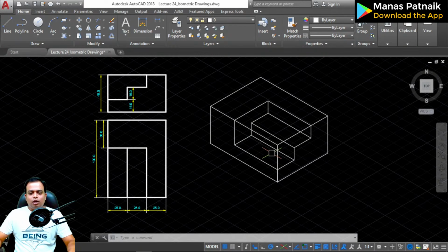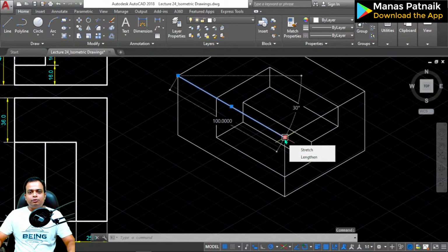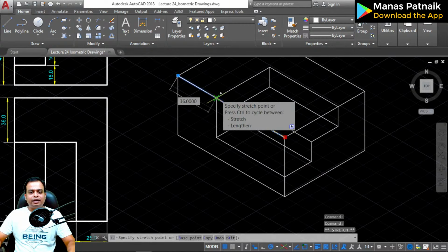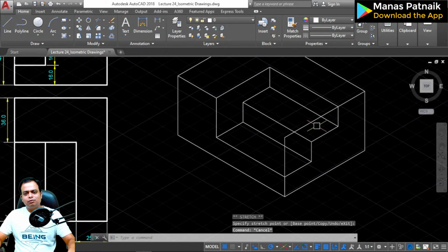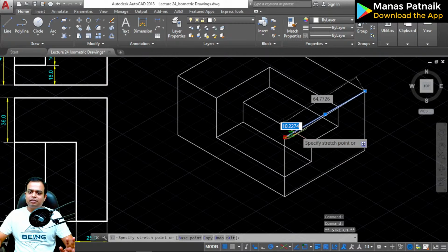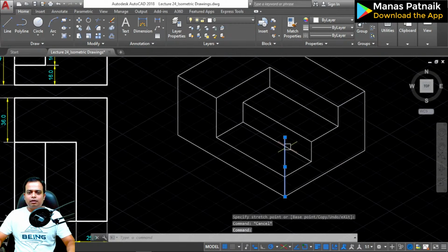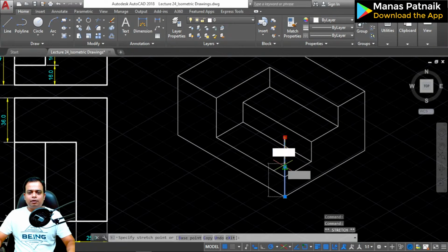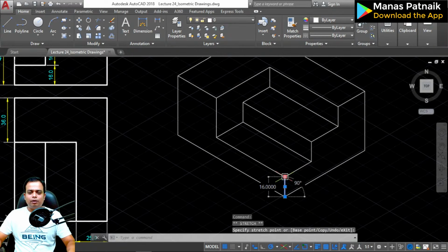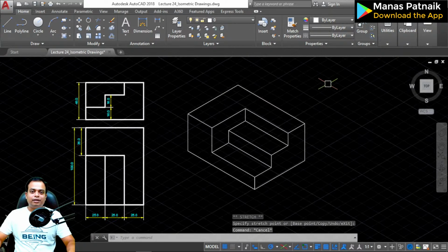Okay, so far so good. Now students, what I'll do is I'll simply go over here. Can you see this grip? Yes, sir, we can, and take it over here. Simply, no problem. Use this grip, click on it. Okay, release, and then go over here, click again. It is going to automatically snap. Click on the grip, move it downwards and take it over here. Lovely. So this is exactly how you can create isometric drawings.